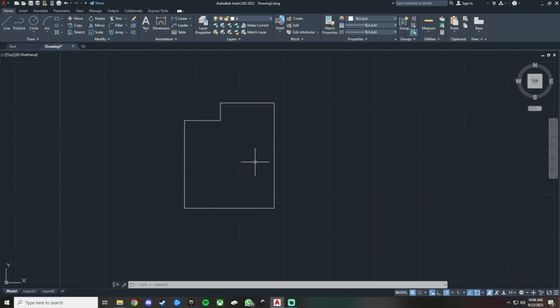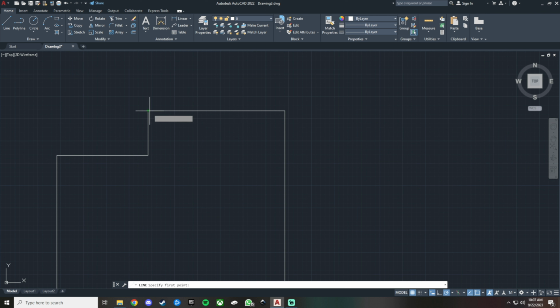So I'm obviously not drawing this floor plan to any specific dimensions or the right dimensions at all. So anyway, let's go ahead with offset. Now that this is a floor plan, we obviously need to make our outside look like walls. So instead of measuring, like let's say this double wall is 2.5 millimeters thick, and instead of drawing another line that says 2.5 and then drawing it across, etc., what we can do is, let me quickly erase that.